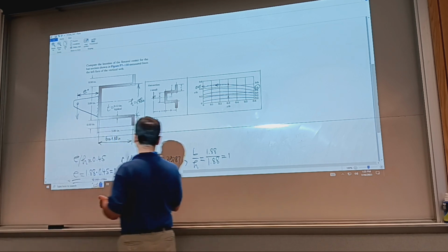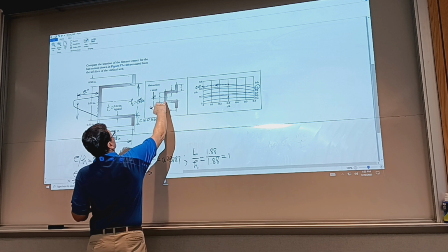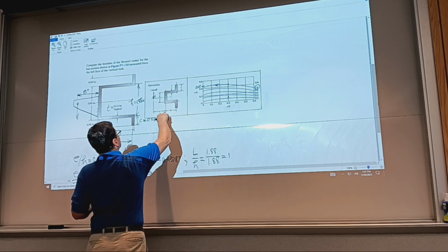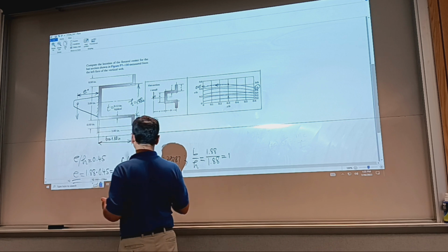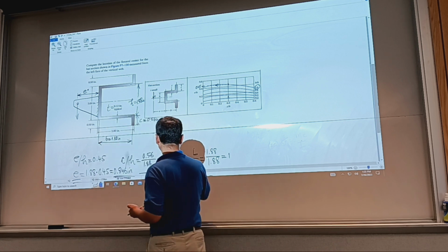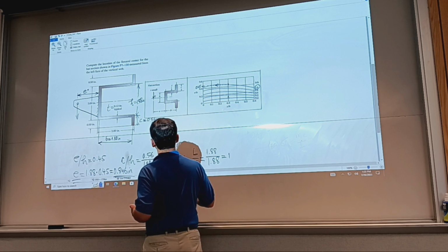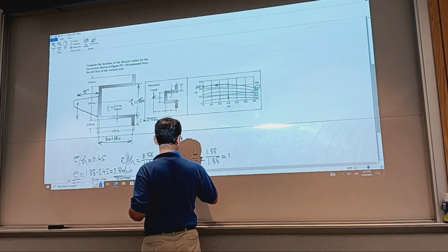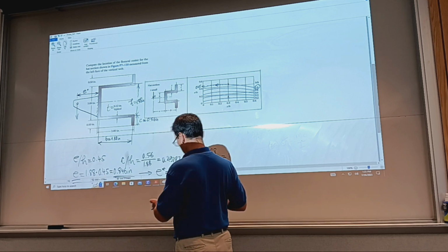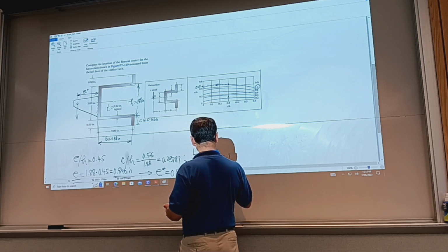So it means that E star, looking at the figure, is going to be the chart's E minus half thickness. So our eccentricity is going to be 0.846 minus half thickness, that is 0.06. So minus 0.06 equals 0.786 inches.